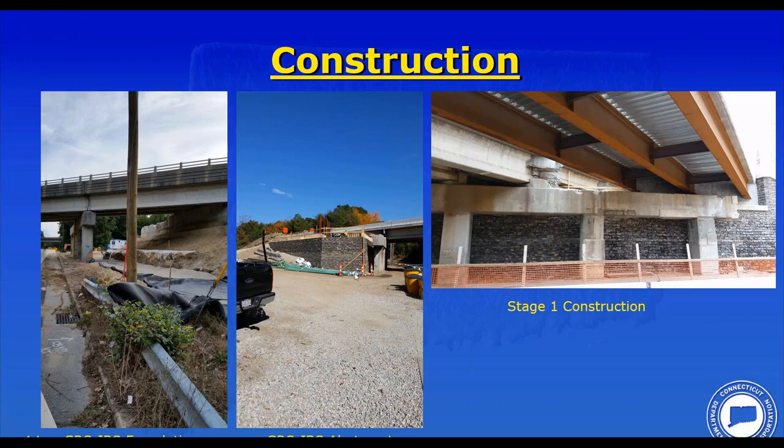Once you start building the bridge, we're using blocks here that can be installed by hand, so we're not looking at heavy equipment. So we could build this entire abutment, I should say a majority of this abutment, underneath the existing bridge before we start closing the bridge upstairs and going to stage construction. So that is a form of ABC. It's an ABC method being applied to a non-ABC project. So we're building as much of the structure offline before we start impacting traffic.